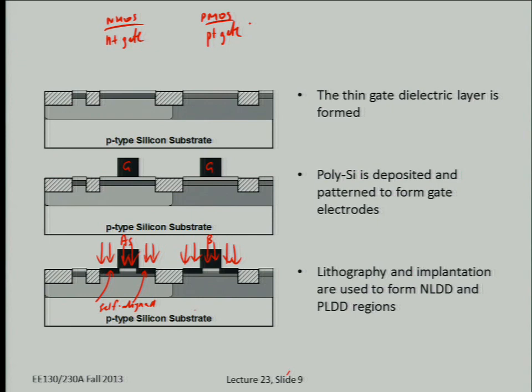Okay, so the typical process is to form the gate first so that you can implant and form the source and drain regions that are self-aligned. Now, why is it important to form the gate self-aligned to the source and drain junctions? Yeah, so the problem is, what if you fabricated a transistor that looked like this? It wouldn't work properly, right? Because you form an inversion layer. Okay, so how are you going to get... I mean, you're going to have some really highly resistive semiconductor region here for current to flow.